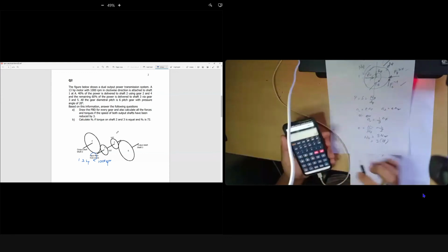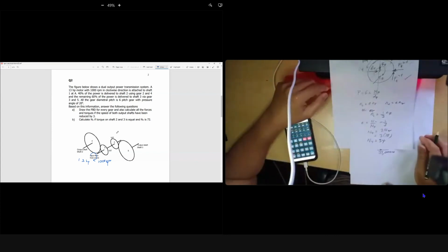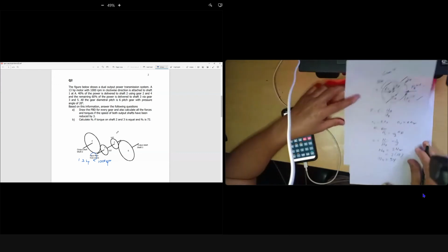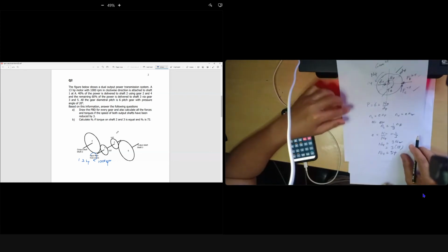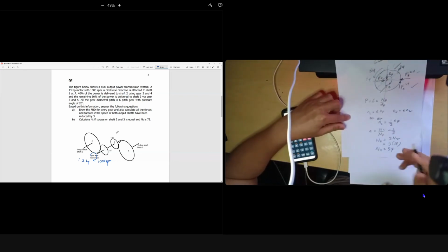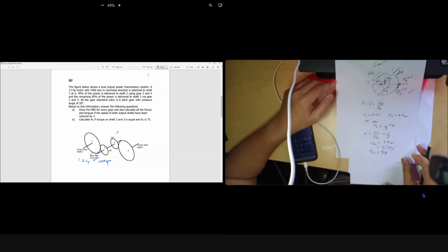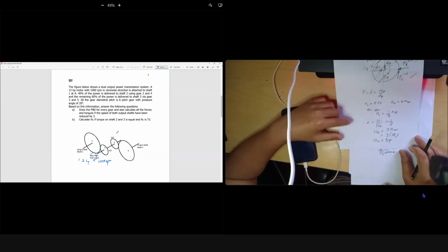Doctor, later we calculate gear 3 and gear 5 with the same method, right? Okay, I'm talking about gear 4 first. Be careful. For gear 4, because N4 is not given, but the statement says speed reduced by 3, it means your 18 number of teeth times 3 is 54. So the number of teeth of your gear 4 is 3 times bigger than that of your gear 2. That's all. You reduce speed by 3.